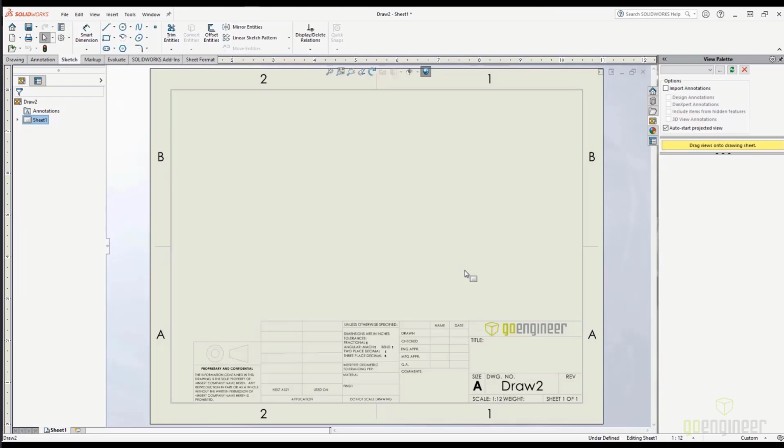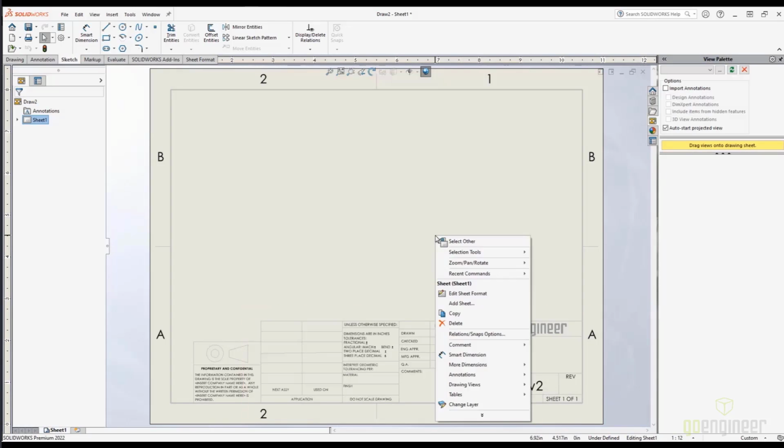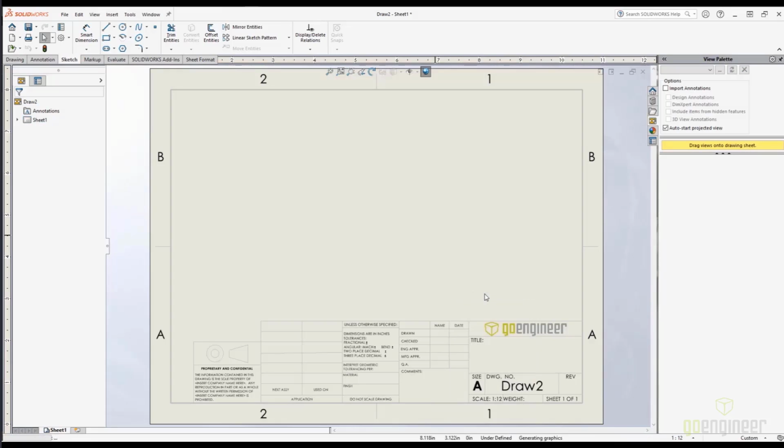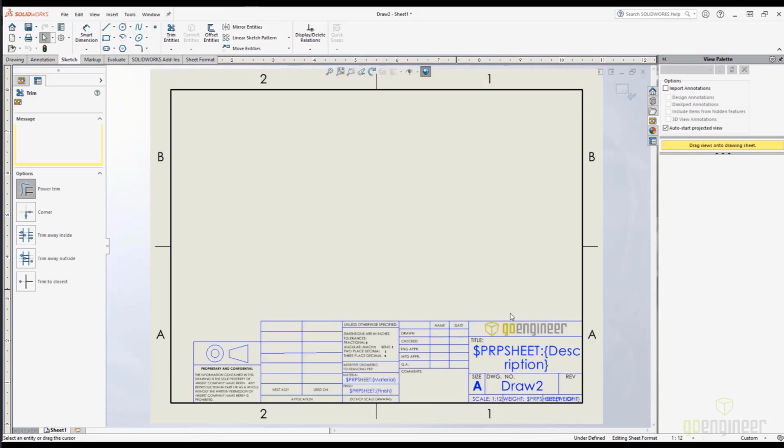When I was working in industry doing this project with our drawing templates, our standard was that the second page of the drawing had a view that was just this lower quadrant of the screen. Everything else that you see was removed, so all the relevant drawn by, checked by had to be on the first page, but the second page really just needed the title and the information here. So what I'm going to do is show you how we created that